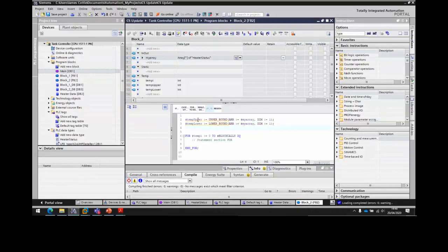And in terms of how my for loop would look, I'm just going to be saying from lower bound to upper bound, go ahead and do whatever we're doing inside of my application. A completely scalable function block that can take an array of any size, which now means that my applications can be scaled up and down depending on my customer's needs, and I don't need to make any changes to my application code. Because it's universal in terms of its access. So this is a cool feature that we can use for dealing with arrays, and a bit on SCL there.